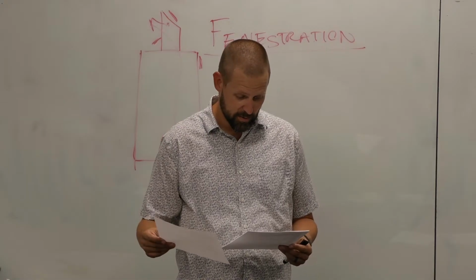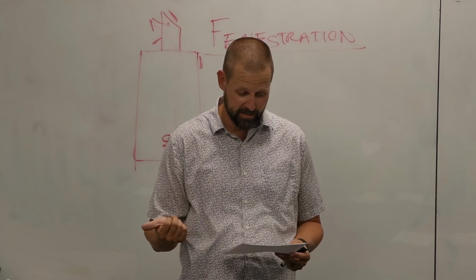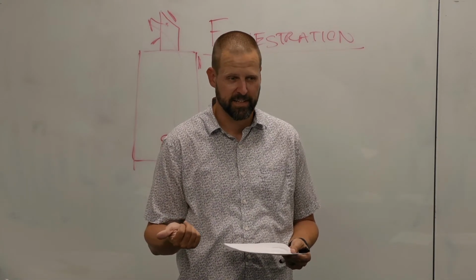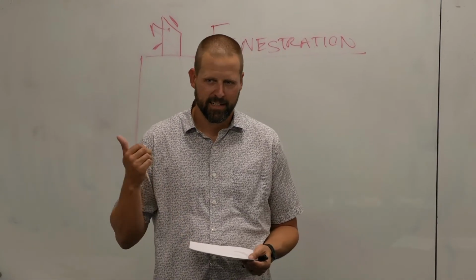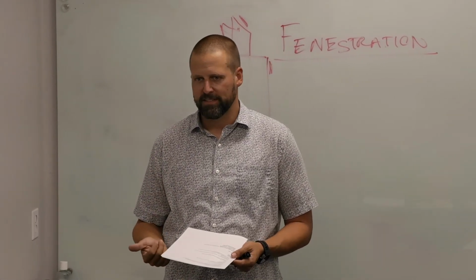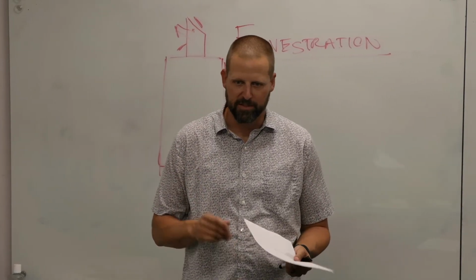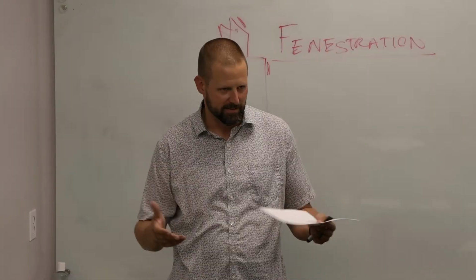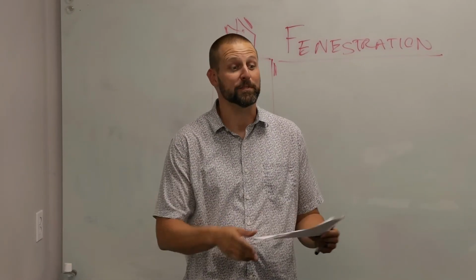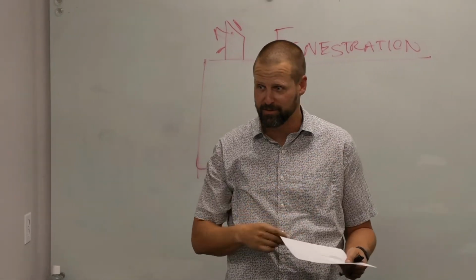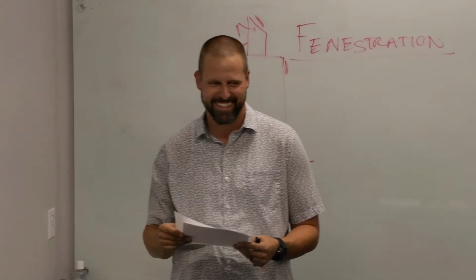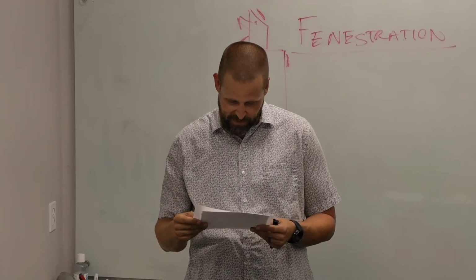Next time we will talk about some practical load calc procedures and estimates. I'm thinking like CFM per square foot, CFM per mullion, BTUs per square foot. I know a lot of the PMs are using it for estimating stuff, so I'd love to have that conversation. So come ready with that. Looking at a few of you PMs.